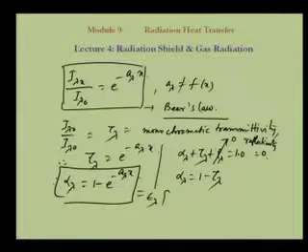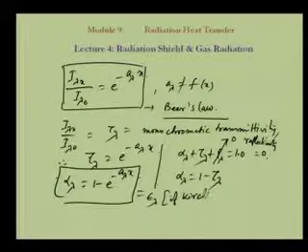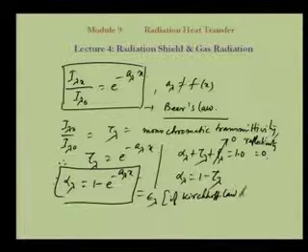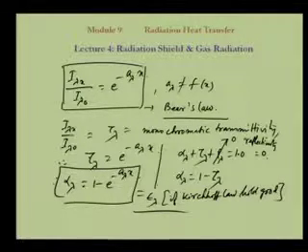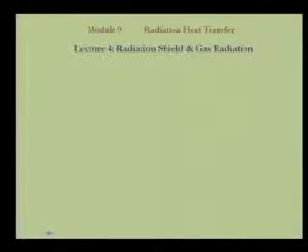This is nothing but the monochromatic absorptivity, and this also can be written as epsilon lambda if Kirchhoff's law holds good. So this is also called the monochromatic emissivity, and this is the monochromatic absorptivity. Now this x is called the length. When we have the length of the beam, for x equal to L, then it will be L. So this x, the length of the beam, is very important,